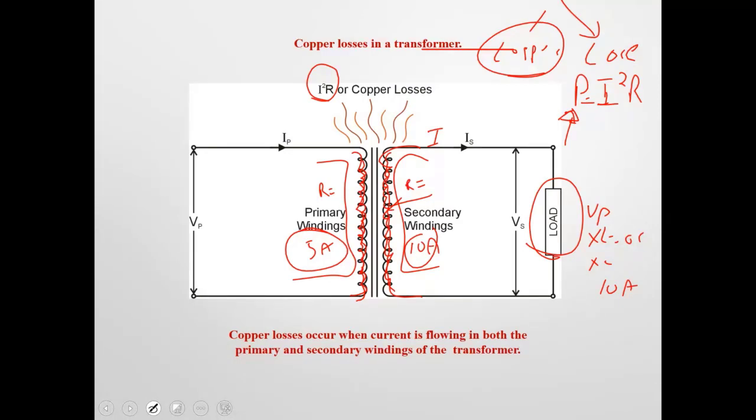So whenever we're looking at a load on a transformer, we need to know the total current of that load. We don't care if it's in phase or out of phase. That's why our transformers are rated in apparent power. The transformer has to be able to handle that current, okay? And we can actually figure out the individual power losses if we know the current and we know the resistance of each one of these windings. So this could be for the primary, okay, then we can multiply it out and find the actual power losses, Cu loss, on the secondary. So it is very much determined by the amount of current flow through this transformer.